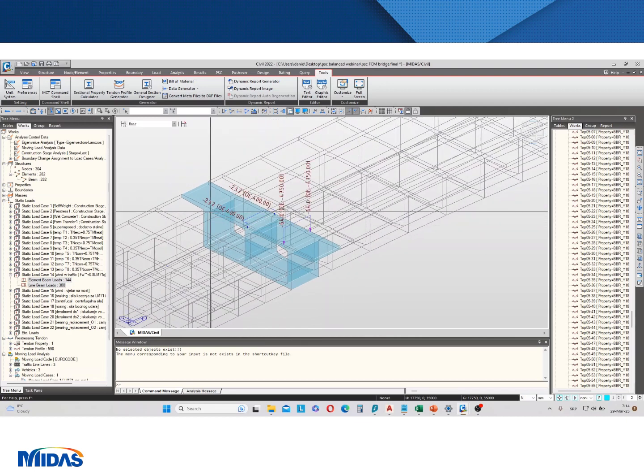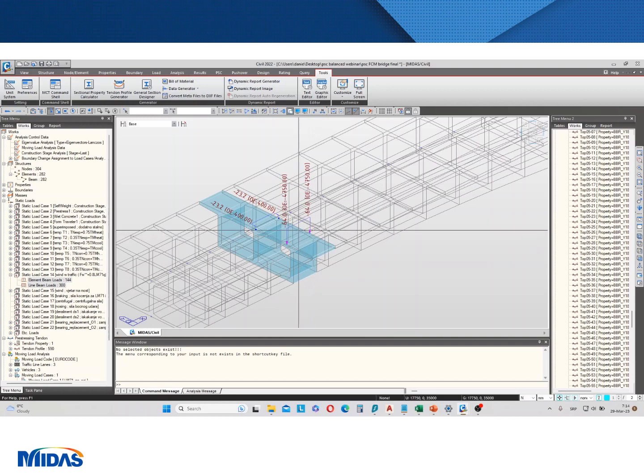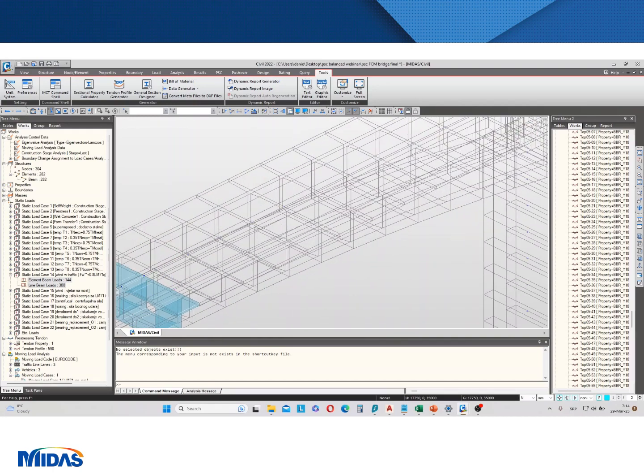So now you can see actually that we have lateral force of the wind here 23.2, with at the same time we have only one load model 71 with psi factor, so it's 80 multiplied by 0.8.